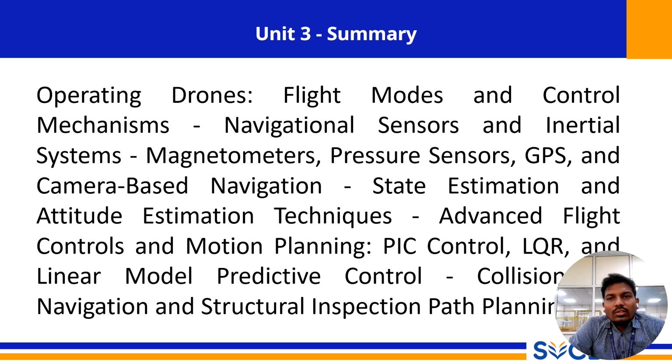However, this reading is susceptible to interference from the drone's own electronics, requiring careful calibration and mounting. Next, pressure sensors provide critical data for altitude and airspeed.